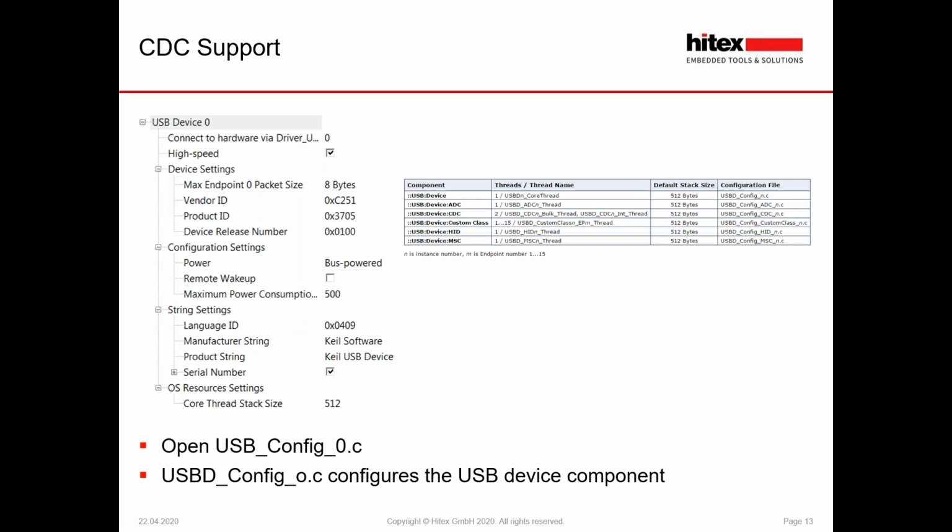In the early days of USB, you had to define all of the descriptors, which are basically arrays of numbers. If you made a mistake in that, then it would just fall over, or if you're using an earlier Windows, it would blue screen and crash. So here we're configuring our USB peripheral, and then these values are automatically used to generate the descriptors. It does make life an awful lot easier.